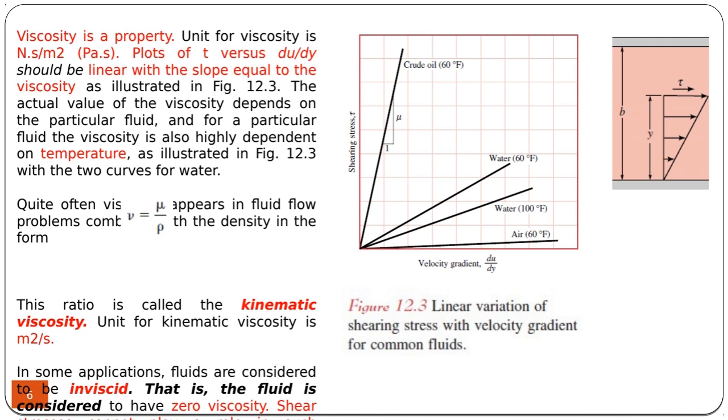Similarly, when you start the engine of your car, the viscosity of the oil is very high because it's very cold and it's very thick. But after a while, when it's warmed, it will be thin. So it's important that the type of the oil is correct. Otherwise, when the engine gets hot, it may not be so easy for the oil to lubricate the engine. This is why the type of the oil is important.